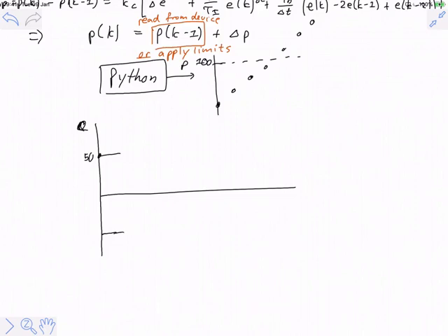Make a very small set point change of like 1 degree and see how that bumps up and see whether the controller behaves the way that you expect. That way you've checked that you've correctly done your implementation. Also remember, when you're doing this with the smooth model, you can use very small time steps, which will allow you to verify that you get exactly the same behavior as the same controller that you approximated continuously.